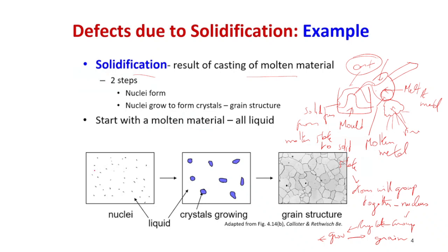It's actually abrupt. So the reason why it's abrupt is, when we are taking nucleus, it's a very small structure, atomic structure, okay? Atomic, or what can I say, nanostructures. So what will happen is, the surface to volume ratio, right? The S to V will be very high. So that means that these atoms are of high energy with free bonds. So because they are having free bonds on the surface, they will attract more and more atoms together. So they will quickly form these nucleus. I mean, these crystal growths.